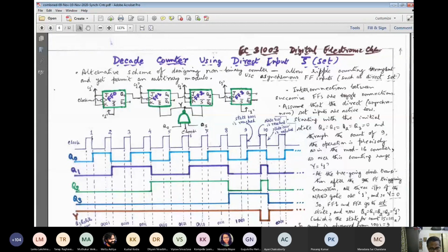Similarly, 7476, although you have not used it maybe, provides two JK flip-flops with 1 to 0 transition triggered clocking. That also has a preset input and a clear input. That preset input and clear input override the data input and the clock input. So when you set it on, making it active, it will make the flip-flop set or reset. Preset and clear should not be made on simultaneously. They should be activated at mutually exclusive times.